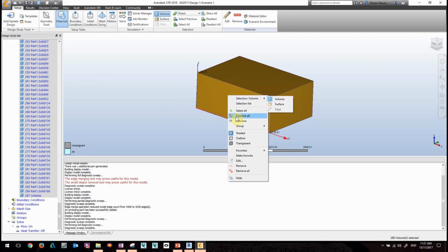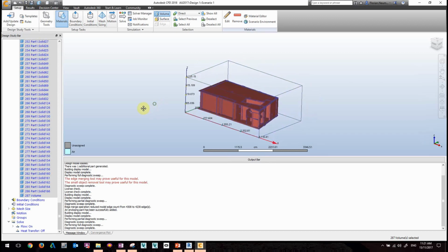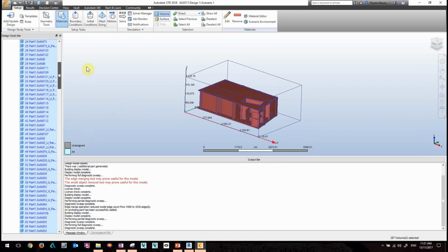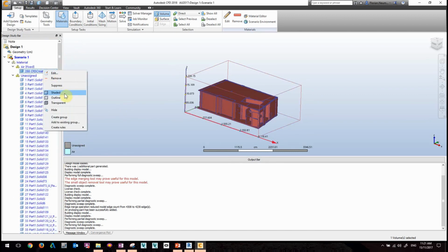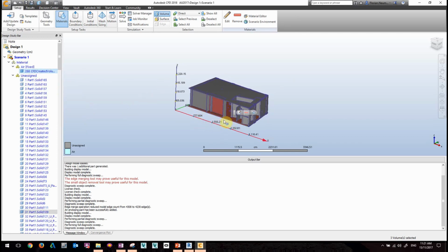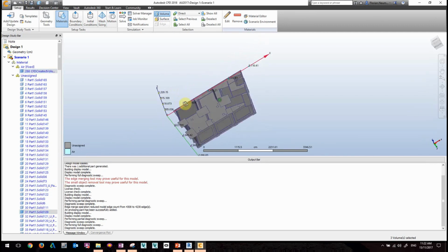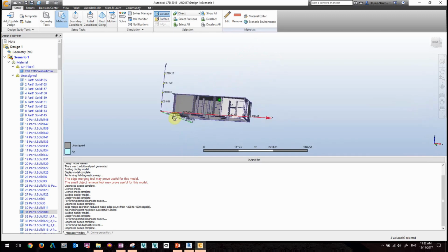And for instance, when you select this, I quickly go to the outline, and then you can also select your model inside. If you don't like this, we also have the option to temporarily hide it. Quickly hide this whole material. Right mouse click, then we can show it again, and then we can touch up our material. So, for instance, I can go to my floor. You see the floor highlights, and I go to hide, and then I can see this from the bottom, orbit this quickly, and then set up my boundary conditions.